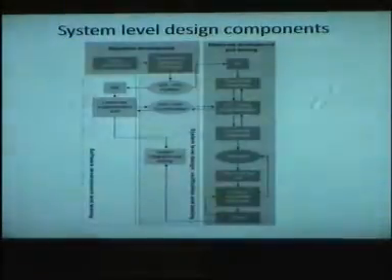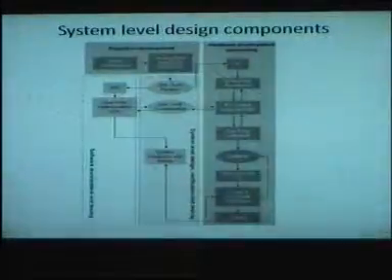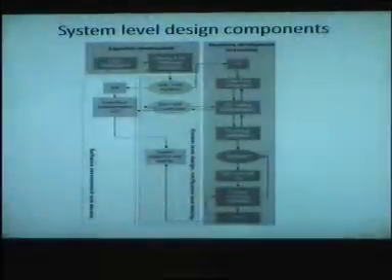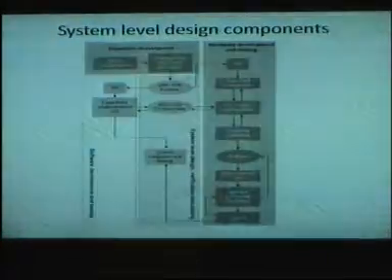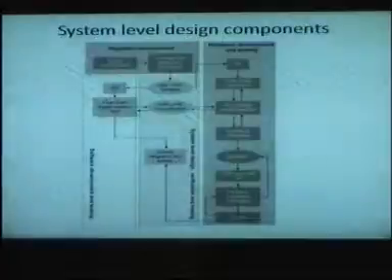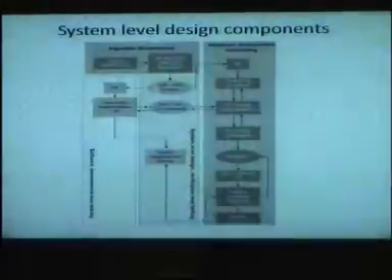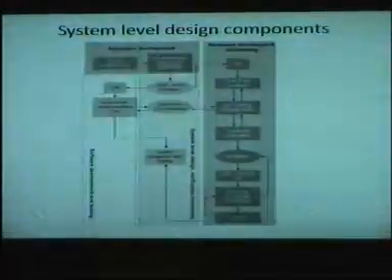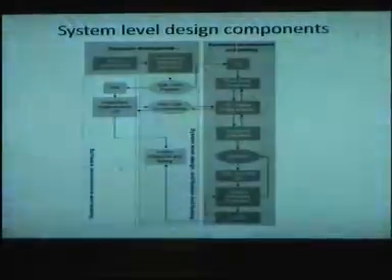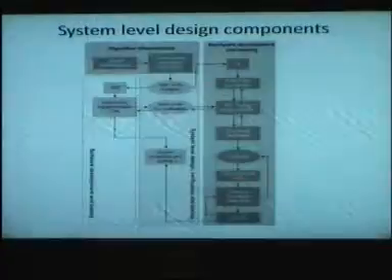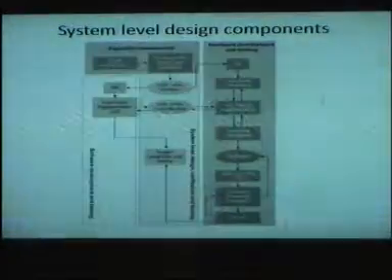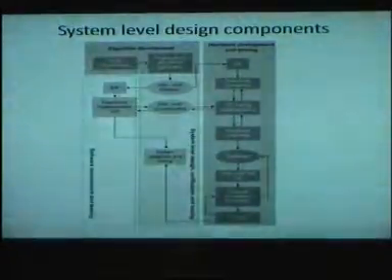Sometimes it is better for them to know that what they are developing needs to go in hardware. So hardware affinity, developing algorithms that are hardware friendly, is very important, because in hardware, if you are dividing so many times, it's impossible. You are giving an impossible task to somebody to put so many dividers. So division is usually avoided, and we try to figure out ways to use minimal divisions.